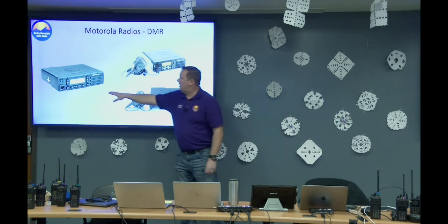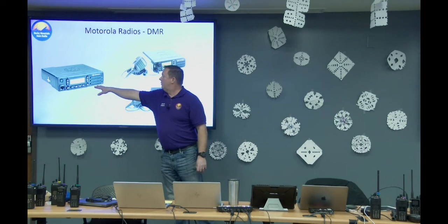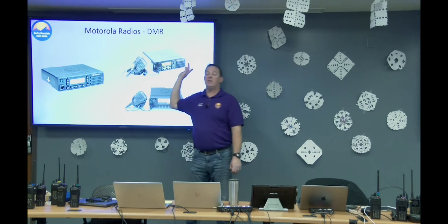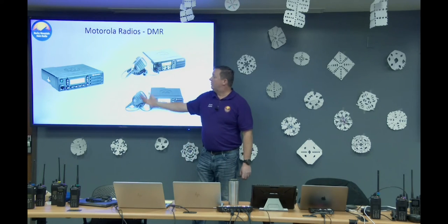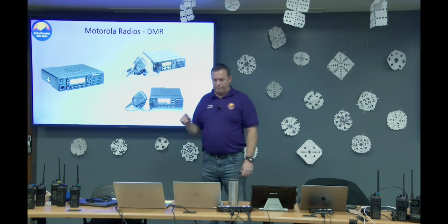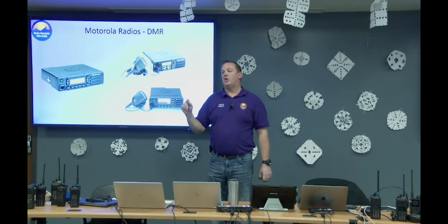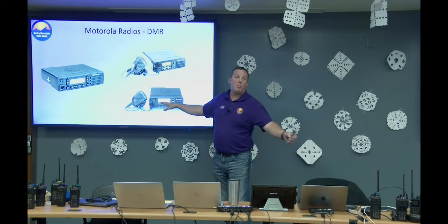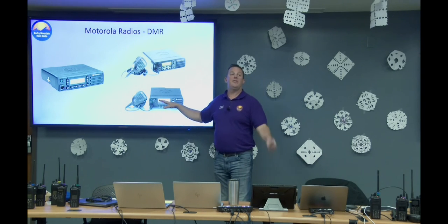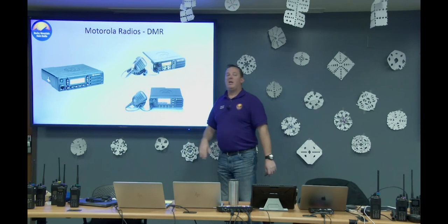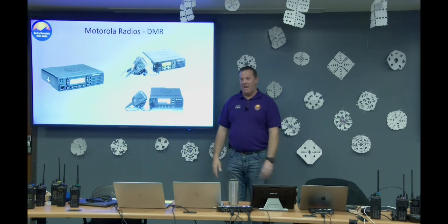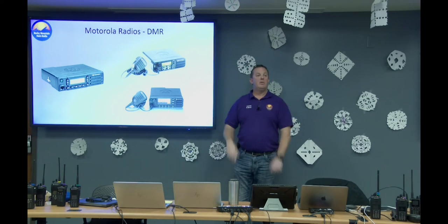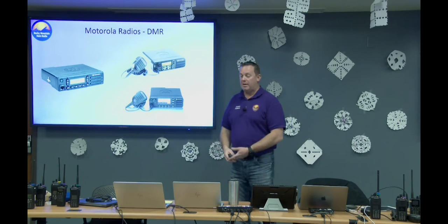And then this is a XPR 2500, which is also analog DMR. It is a 99 channel radio. These are 1,000 channel radios. But excellent little radios. Again, the caveat with the code plugs: if you have an XPR 5550E low power, it uses a different code plug than the 5550E high power. Code plug looks identical every single way through, except the power level is different. So you have to copy paste or start with a plug that supports that.